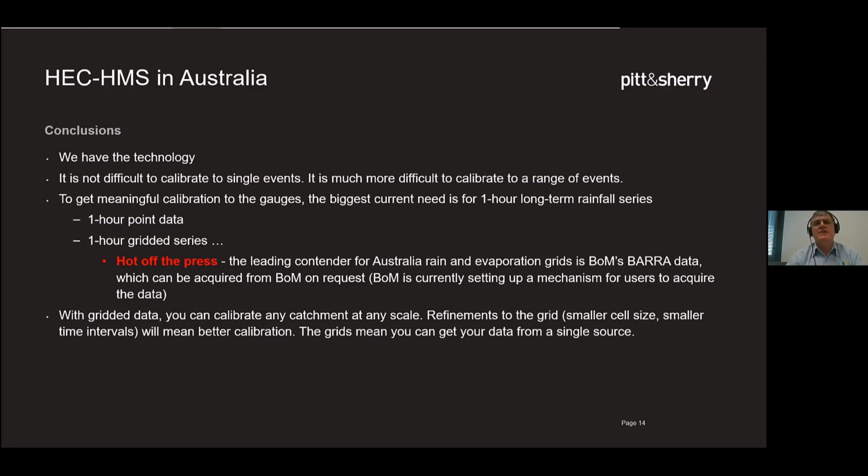And I know the HEC has been developing this technology so that you don't just need grids for rainfall. You can do it for evaporation. You can do it for your soil losses. You can do it for your fractions impervious. You can do it for all your soil parameters and so on.